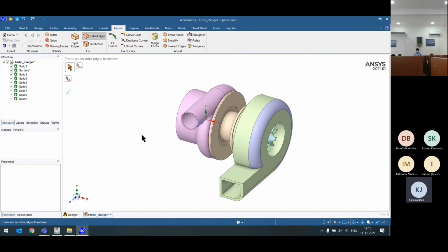Okay, so this is remote. Now what you need to do is again check, so whichever objects are visible, only for those will the command be executed. Okay, that you need to keep in mind. Now again I have made all the objects visible, so I need to perform this command. Okay, and again you can see it is showing one area found, somewhere on this flange.